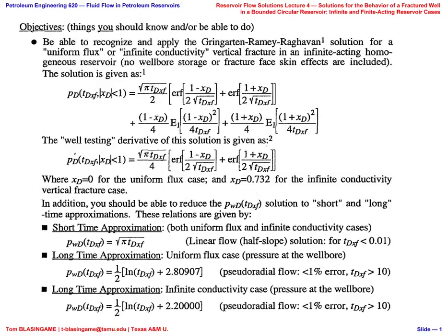And even now, whenever you're hydraulically fracture stimulating well A, over in well B it starts producing sand, because you're literally injecting it thousands of feet away and it's going into that other well. But for the sake of argument tonight, again, all we're talking about is a single vertical fracture. It could be created just with water. This is called a slick water fracture treatment. They put chemicals in it, obviously, to reduce viscosity and so you don't react with the formation and that sort of thing. But it's a lot cheaper to just pump water.